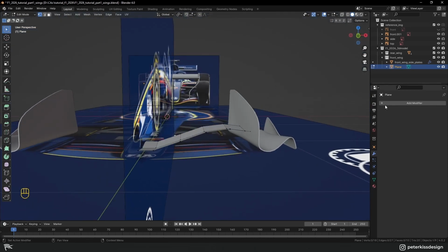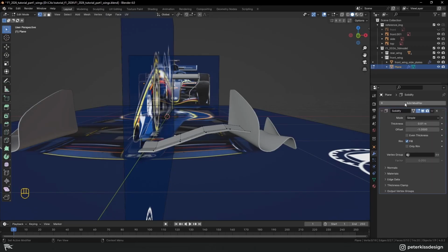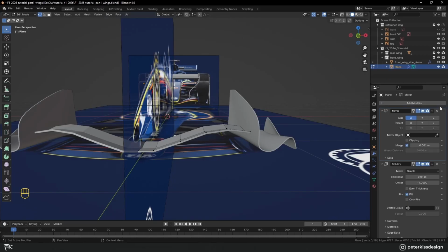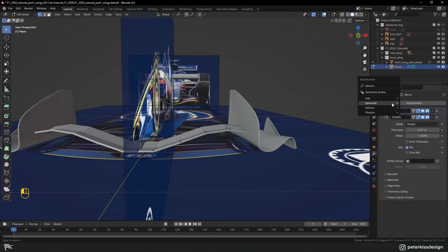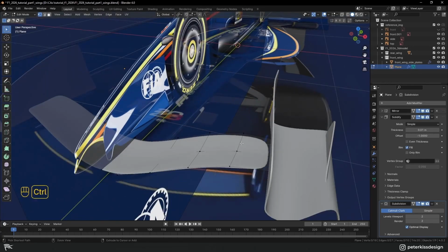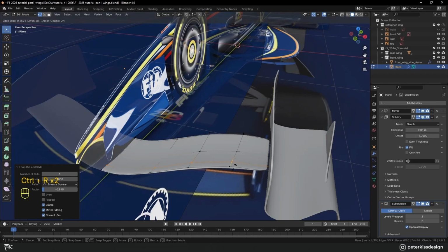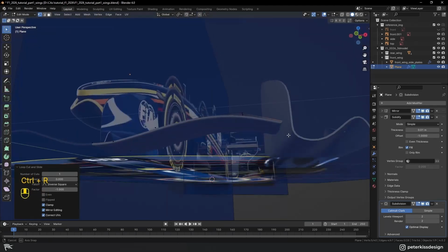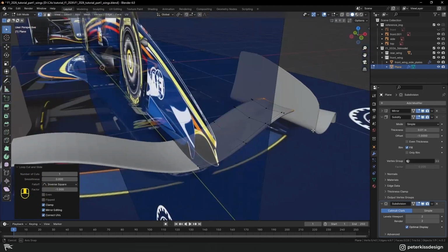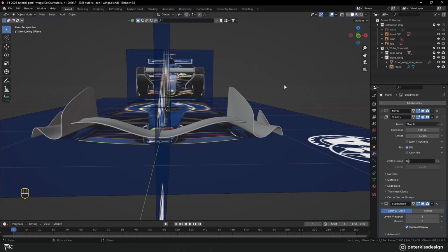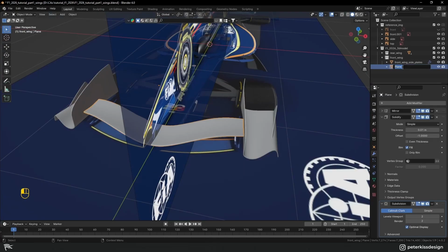Let's add a solidify modifier. Let's add a mirror and move it before the solidify modifier because we want to mirror first and then add the thickness. And then add a subdivision modifier. Add loop cuts to define the edges, and add 2 loop cuts here to define the side. Okay, go to Object Mode, right click, Shade Auto Smooth. We have the first part, and this way we will create the remaining 2.